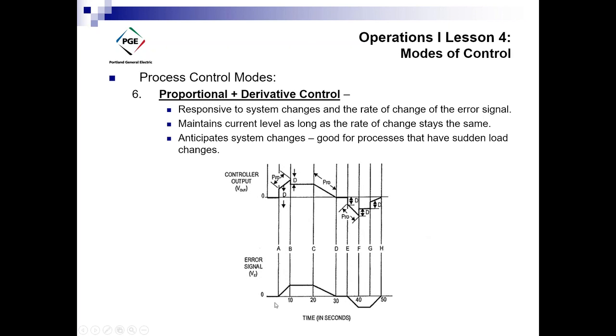So here's a really good example now. So you've got this. This is not an instantaneous error signal. It's a ramping up error signal. So you'll get an initial, see, the D is for derivative. So you get this is the derivative part of the control signal, then proportional increase. Derivative drops off. Now you've got a constant control output and a constant error signal. Now it drops off proportionally. So that's the proportional part here again. 0, 0, and then of course the reverse in the negative direction.